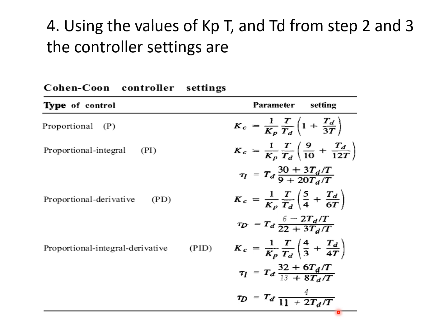So basically, two conventional methods: the closed loop method of Ziegler-Nichols, and this open loop method of Cohen-Coon, to get controller settings that you can use, theoretically or in simulation, not just by trial and error or randomly, to find the best controller for your system. Of course, for most of them, you need to have certain conditions. For Ziegler-Nichols, you need to get continuous oscillation, which sometimes is quite difficult to get.